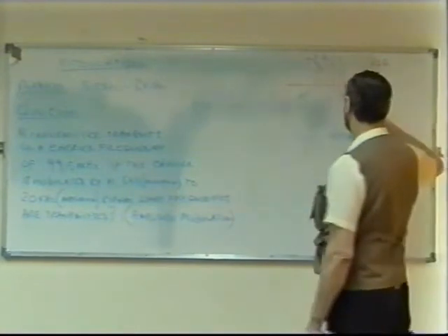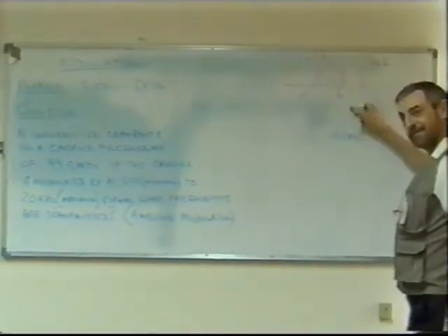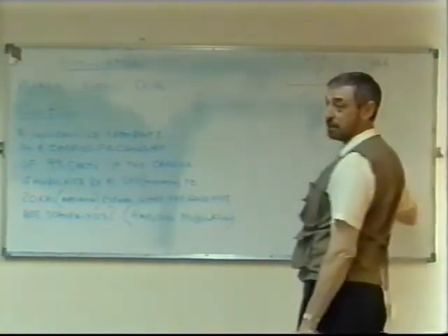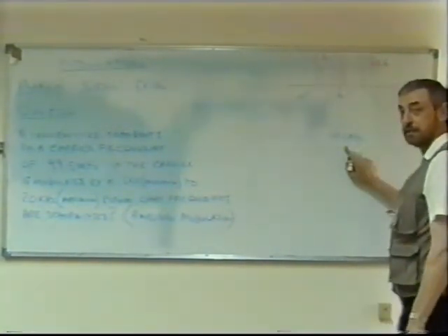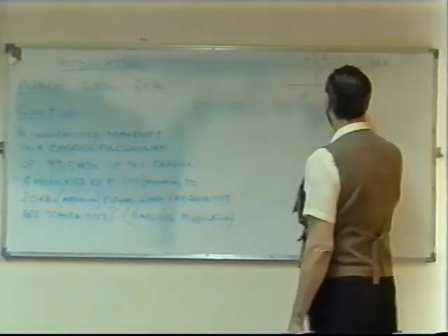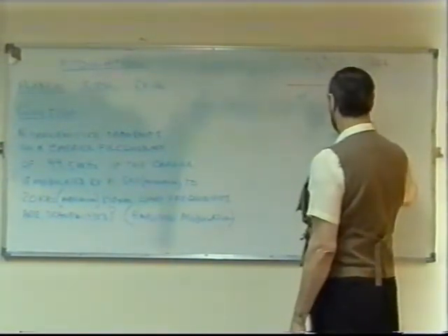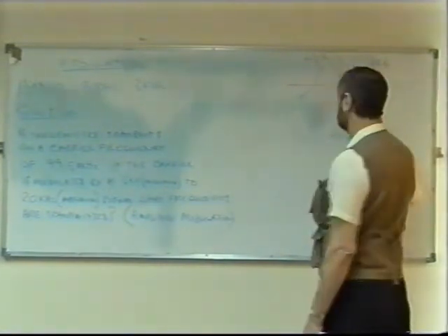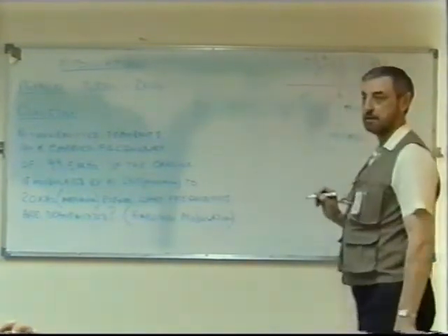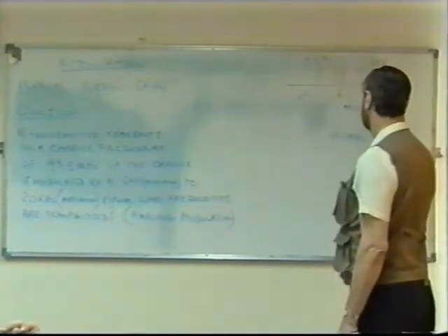Plus 5, no. It's 0.005, not 0.05. 5 kilohertz, yes, that's right. You don't forget your decimal points here. 99.5 plus 0.005 will be 99.505 megahertz. 5K means 0.005.